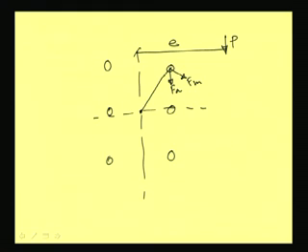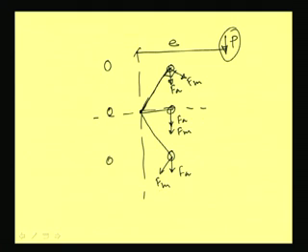So, this F M will basically act at 90 degrees to this. Similarly for this rivet, F A and F M will act downward, and in this rivet it will act like this. F A will always be downward because P is always downward, and F M will be at 90 degrees to the radius.